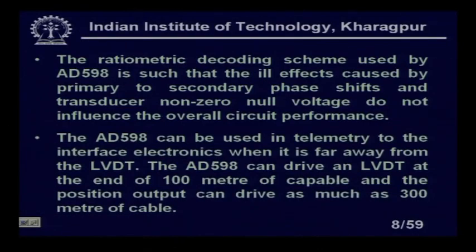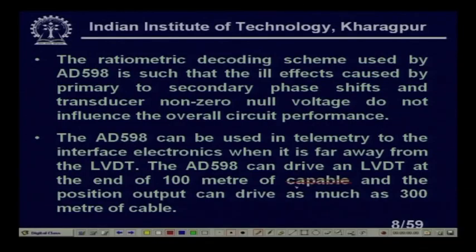The AD598 can be used in telemetry, with the interface electronics far away from the LVDT. It can drive an LVDT at the end of 100 meters of cable, and the position output can drive as much as 300 meters of cable. I think it will be cable, if I am not wrong. So, it will be cable, right.